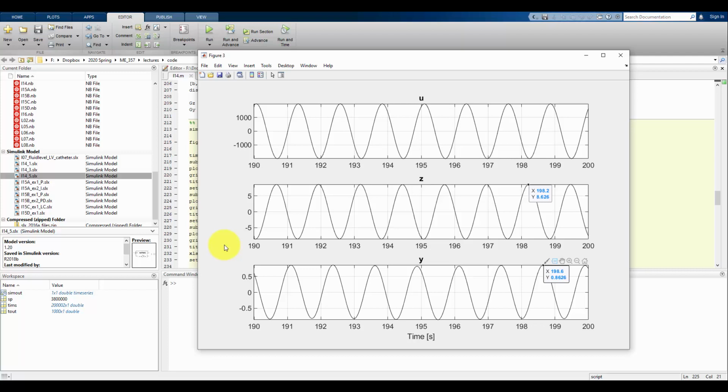So finally, for this multi-degree of freedom system, we were able to analytically calculate what the steady state behavior was going to be for our 2 masses, for the positions of our 2 masses. We did this analytically using a Bode diagram. We could do that because we had only a single simple harmonic input into our system. If that were not the case, we could not use this same technique that we've been using. And then we saw through simulation, using a Simulink model and running our input through that, we have verified that we get those same amplitudes at steady state.